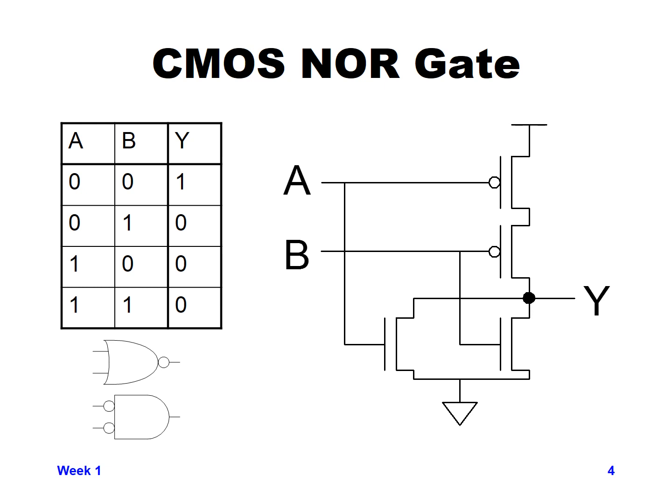So the right hand side shows the transistor level diagram again. If we look at the lower left hand side, we see the symbol diagrams for this functionality. And again, there's two symbols because De Morgan's theorem says that there's two ways of writing the logical function, but they will have the same functional behavior. So one is an OR inverted, so an OR not